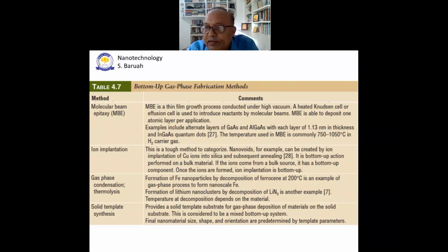So the substrate is kept at a negative potential, all right, and automatically whatever of these ions that are formed, based on the strength of the electric field, which can go up to a few kilo electron volts, you can have a huge force, a huge momentum because of the velocity. Right, mass will remain constant anyway because we are not removing the protons and neutrons. The neutrons basically give maximum mass, right? So the mass remains the same. We have a charged particle and a lot of momentum, and once they go and strike the surface of a substrate with a very high momentum, they will strike away certain material out from the surface.